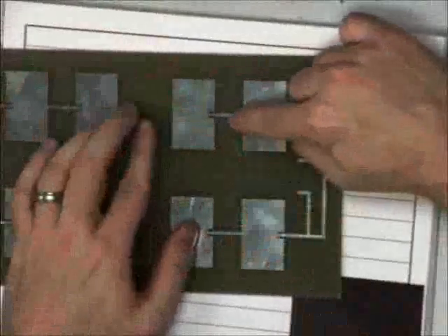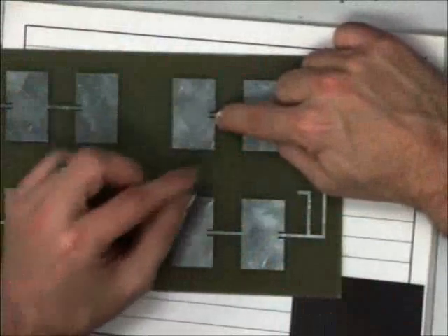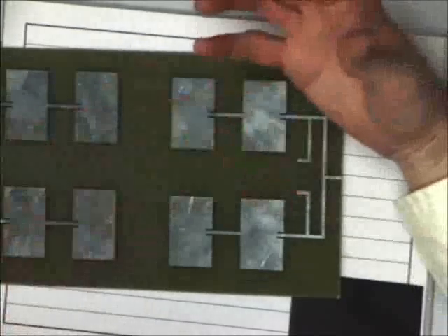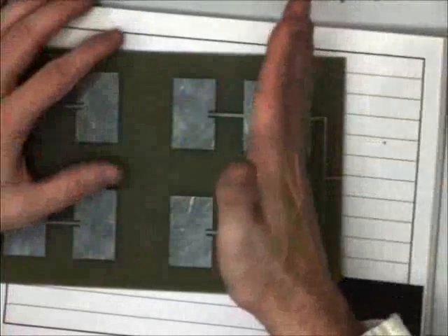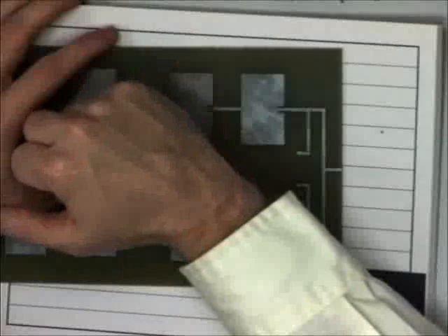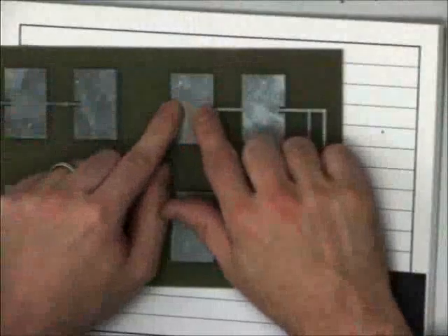Now, if you were just to feed the patch like that and you design this properly, this would look effectively like a purely real load at the end of the transmission line, ideally. And it's not a resistor. What that load physically represents in the circuit model is voltage and current going down, striking the end of the line, dumping into a circuit resistance, which is really radiated modes of power. It's sending power out. It's not ohmic losses, which is what a lot of your low-frequency resistors in a circuit model represent.